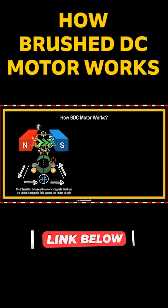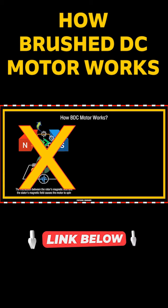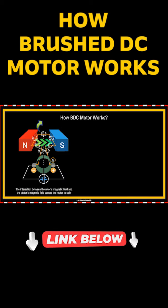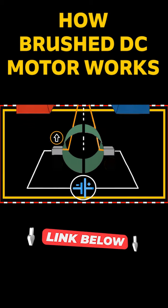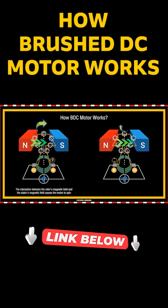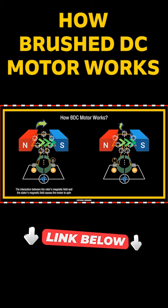However, once both magnetic fields are aligned, the rotor would naturally stop. Now we need another push. We need a change in the magnetic fields in order to make the rotor spin again. To do that, we need to reverse the polarity of the coil, so that the magnetic field of the coil is generated in the opposite direction and keeps interacting with the permanent magnets. But how do we reverse the polarity then?